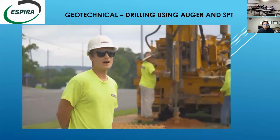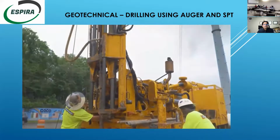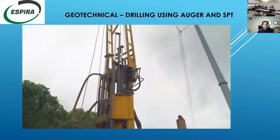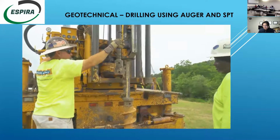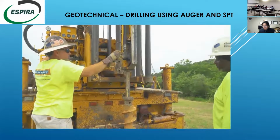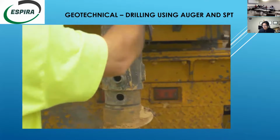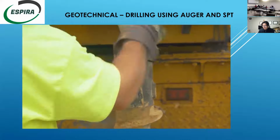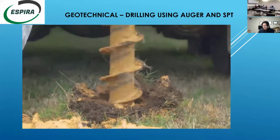So Lee and Terry behind me are currently sampling soil. We sample every couple feet, and what is going on right now, that's a hammer, it's a weight, it's a 140-pound weight, and we know how far it drops, so we can reference that to how hard or soft the soil is, give them, the structural guys, a report, and that'll base their foundation design off our report.